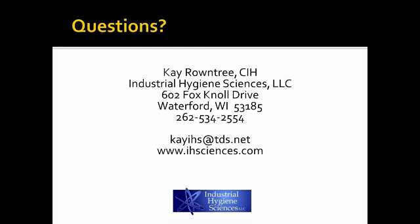But look at the size and configuration of the casting, things that bring the employee very close to it, where the fume is going directly into their breathing zone, or processes that generate a lot of fume. Those are the ones you want to focus on, and the little ones you don't have to worry so much about. I hope that's a helpful answer.